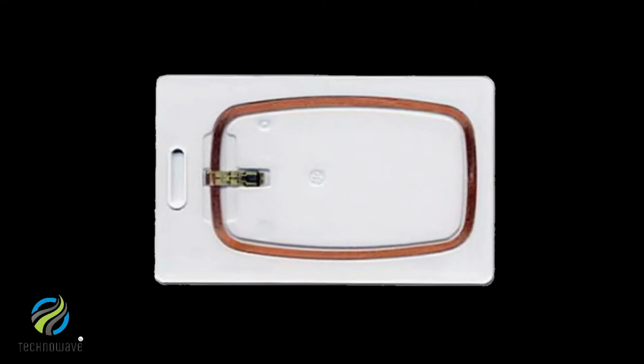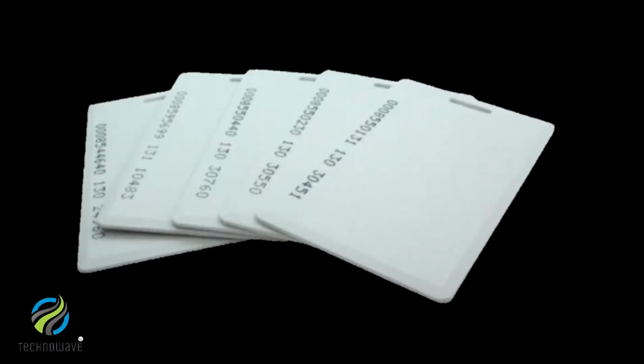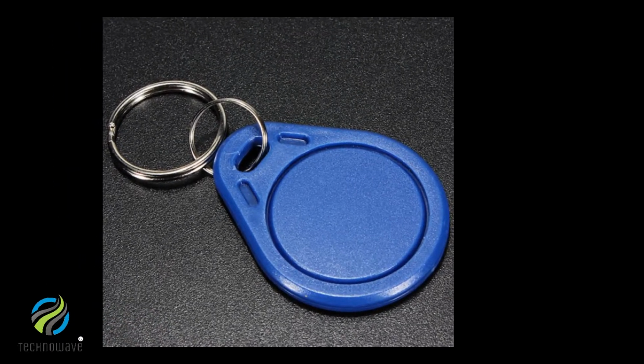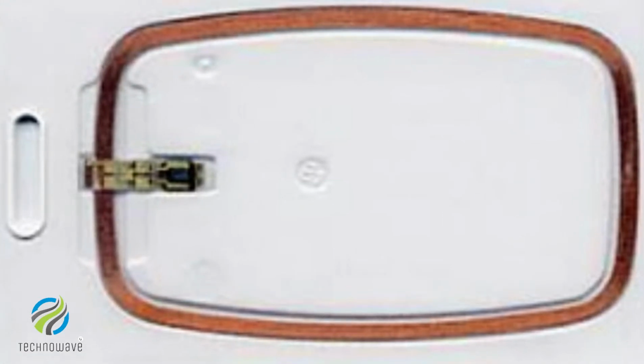Tag: the RFID tag has an embedded transmitter and receiver. The actual RFID component contained in a tag has two parts: an integrated circuit for storing and processing information, and an antenna to receive and transmit a signal. The RFID tag has non-volatile memory storage, and can include either fixed or programmable logic for processing transmission and sensor data. The tag is also composed of a protective material that holds the pieces together and shields them from various environmental conditions. The protective material depends on the application. For example, employee ID badges containing RFID tags are typically made from durable plastic, and the tag is embedded between the layers of plastic. RFID tags come in a variety of shapes and sizes.